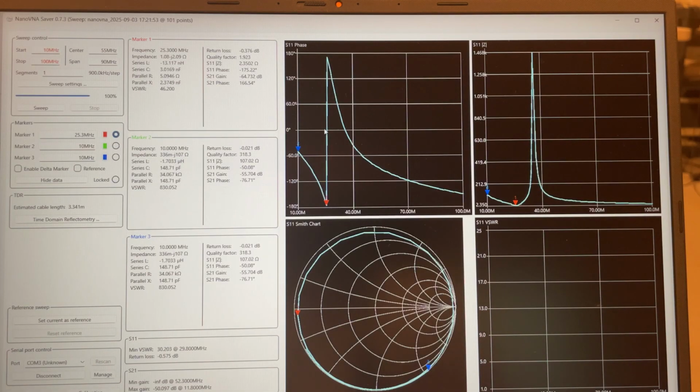So this behaves the same way as a quarter wavelength of coax. With the output, or R load, open, the input, the NanoVNA side, which would be our source, is shorted. So we see 2.35 ohms here.